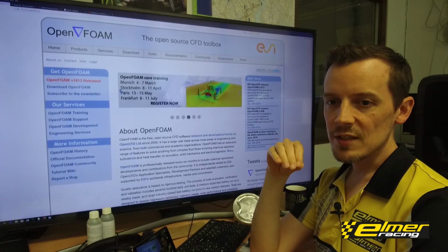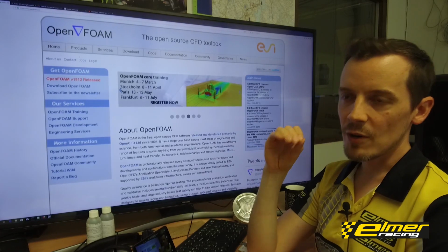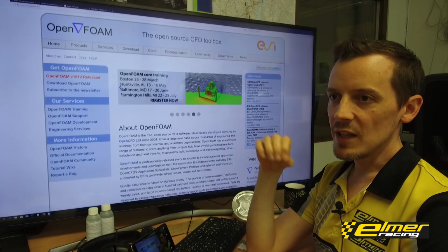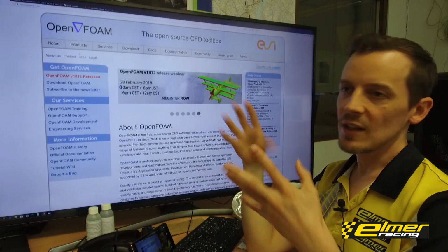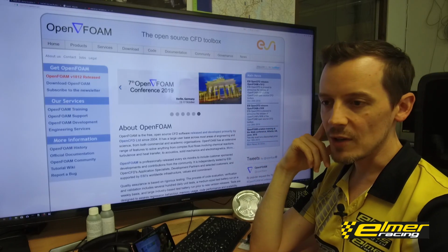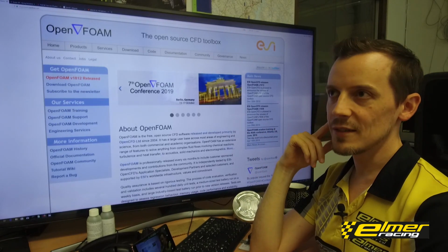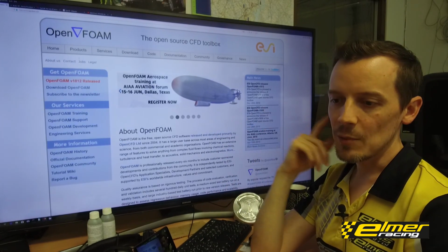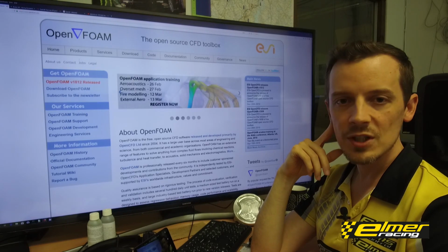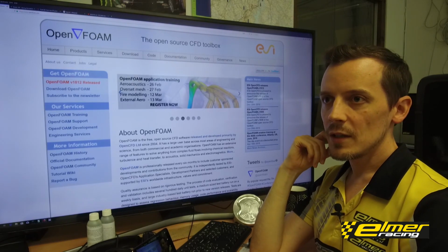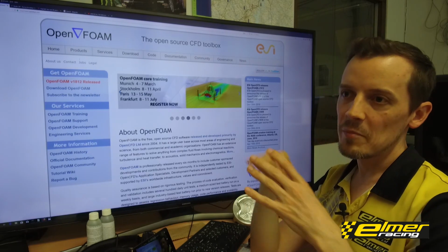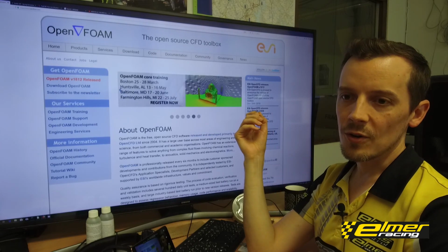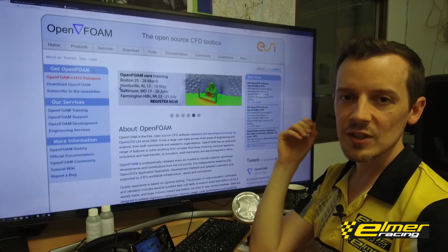So manufacturing techniques are also very important for the project cost as a whole, because you can very easily end up with needing to start 3D printing large parts, and that gets very expensive. If you need to 3D print large metal pieces, then it gets very expensive. Of course, you can 3D print large plastic pieces quite cheaply. And then do you need a milled mold, for instance, to do some carbon fiber overlay, or do you have potentially cheaper ways to do that?